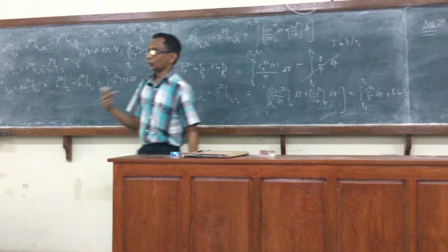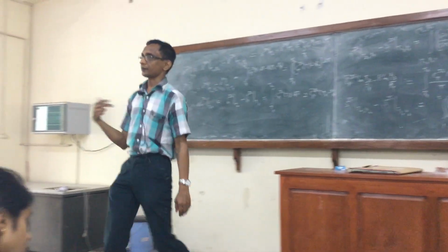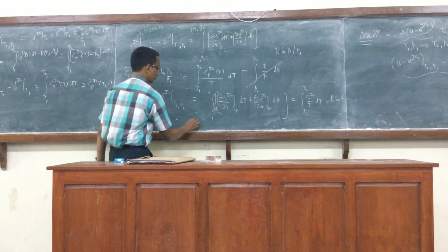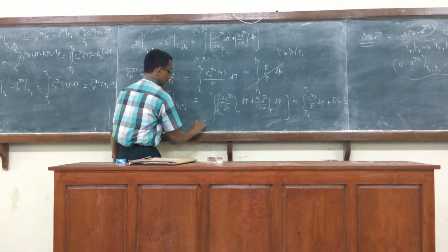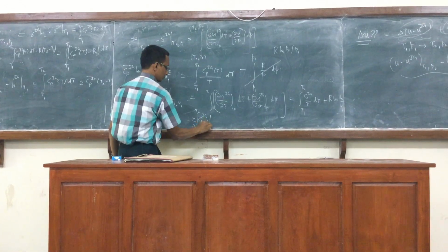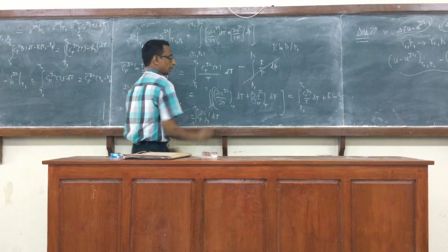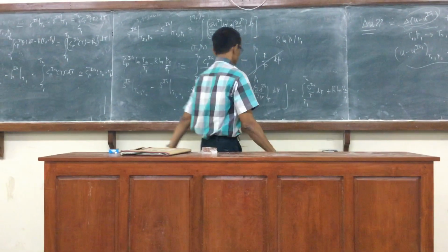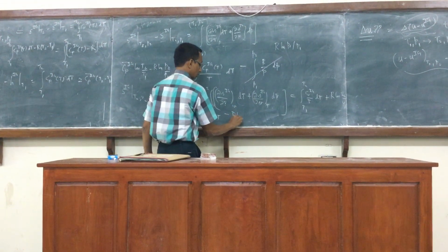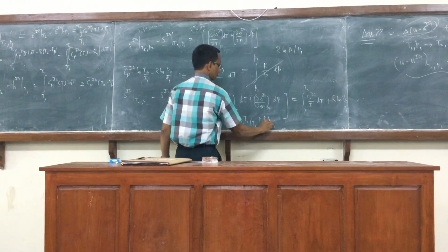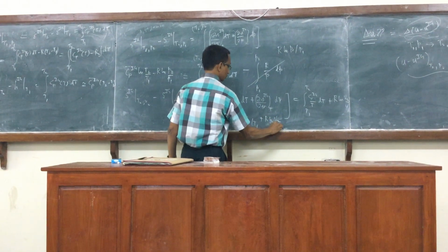Now, however, if you want to express it in terms of the Cp, that can also be done. So this would be Cp integral T1 to T2 of dT by T minus R, that is minus R over T, right? That would be minus R logarithm T2 by T1 plus R logarithm V2 by V1.